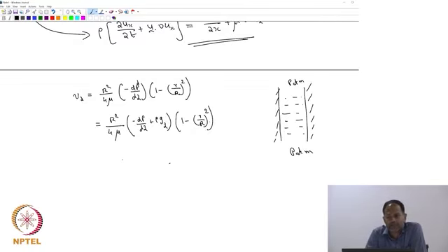That's all it says. On the other hand, if you had applied a pressure gradient in this direction, let's say by putting something below like fluid in a container, then what are you going to do? You are going to apply an upward force, okay? You are going to apply a dP/dz upward, and these two terms will cancel each other when dP/dz is exactly equal to rho g_z, in which case there is no flow. If dP/dz is more than rho g_z, then there will be an upward flow. That's what it is. So it's really that competition that these two terms are showing. That's also clear. Next problem.